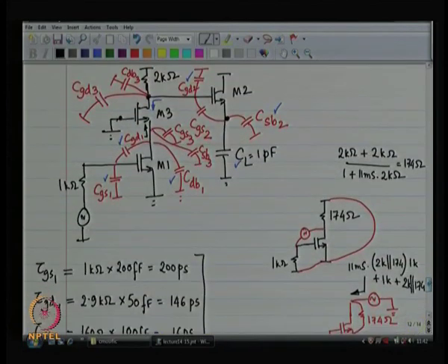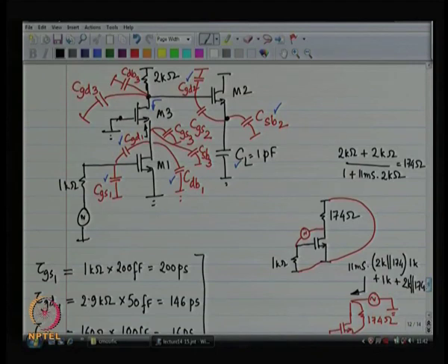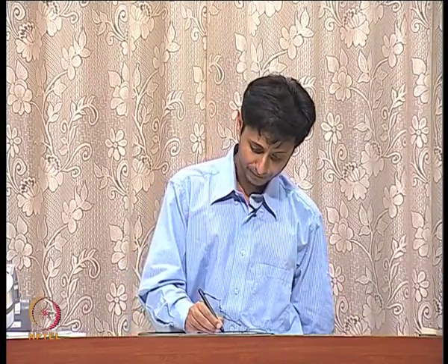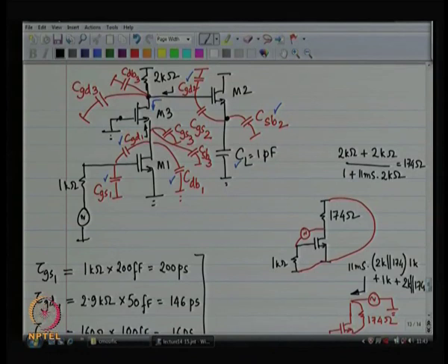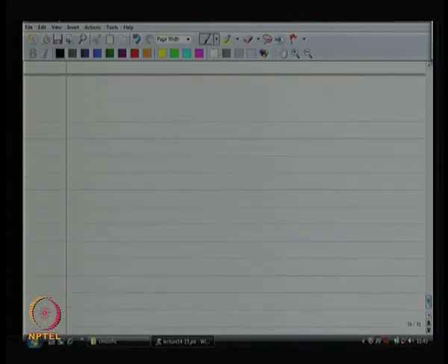All right. Now, the difficult one is CGS2. CGS2, once again you have to dereference the particular node, right. You have to refer to ground as the gate. Now, before doing that, you should remember that the impedance looking in over here is 48 kilo ohms, right. That is an important thing to remember. So, I am going to redraw my circuit to look like this.